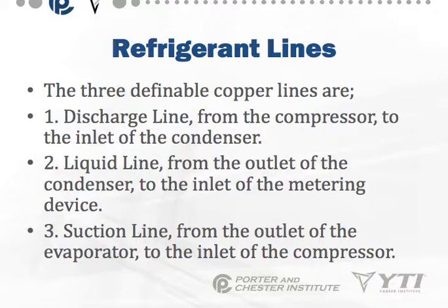You have a discharge line that runs from the compressor to the inlet of the condenser. This one is really hot. You have the liquid line from the outlet of the condenser to the inlet of the metering device. Okay, this should be about body temperature. If you grab hold of this with your hand, you shouldn't burn yourself. It should feel roughly around your hand temperature.